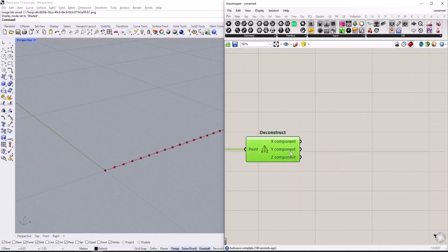point. Again, I want to use these three components to generate a new set of points, so I type x, y, z once more and bring in the construct component. If I directly connect the two x, nothing will be changed and the same point will be recreated. However, I want to introduce some variation.